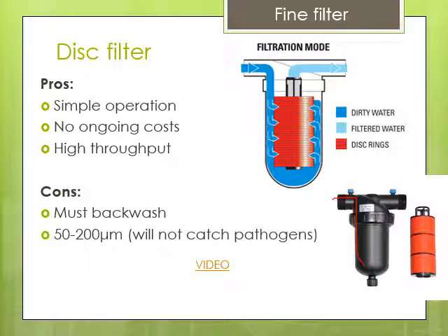I did have one of these in my ornamental greenhouse for filtering so hanging basket drippers wouldn't plug. But I see these a lot more in nurseries because they have fields way out. It's not necessarily a greenhouse. You're driving on a tractor way out in the field, and they run the irrigation pipes underground. Then they come up to different sections where they have risers, and that's usually where they put these filters. So anyways, watch the video to help you explain what they do.